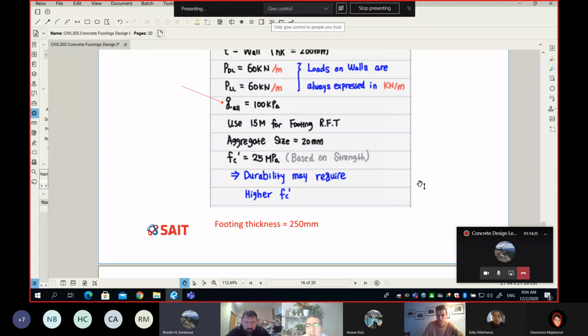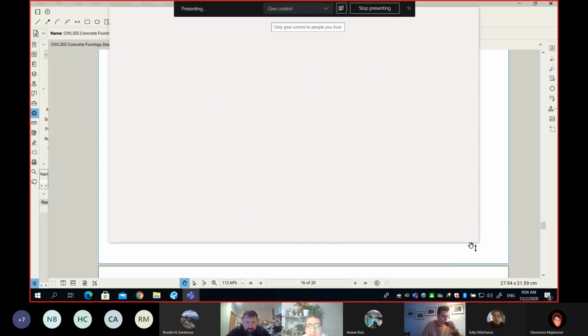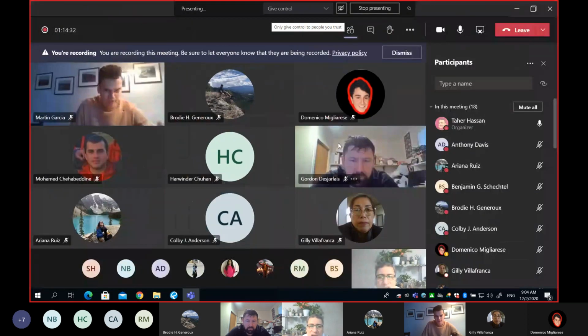Actually, the sulfate is not really an enemy with the steel. So the sulfate doesn't hurt the steel. The sulfate is not a friend with concrete. It reacts with concrete and simply makes some cracks. The one that is the enemy with the rebar is the chloride. Okay?